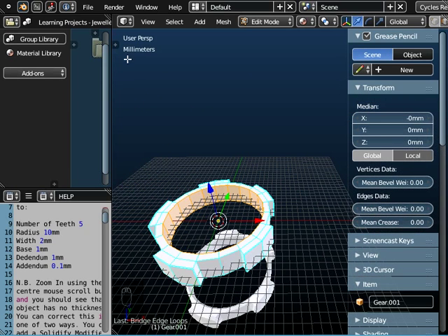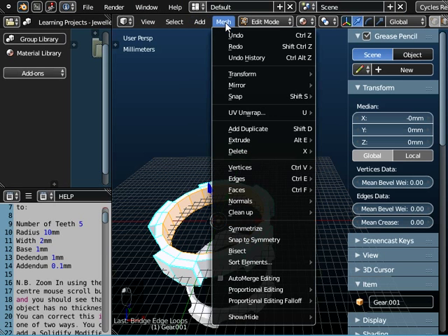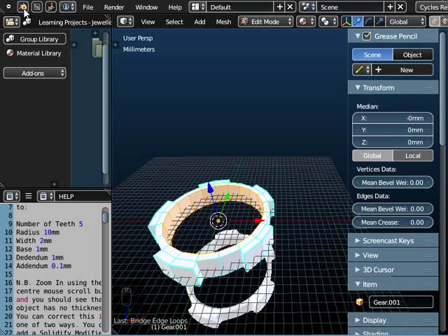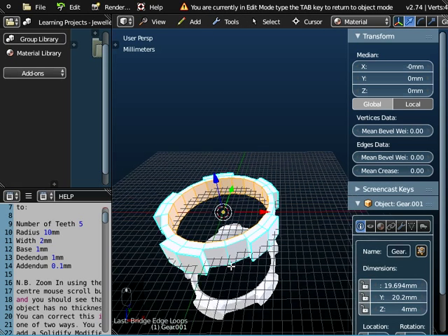Okay, so that's in the Blender menu system. We can switch back to FluidDesigner by clicking on the Blender icon again, and close that down by clicking in the left hand corner. So you can see the menu for meshes has disappeared now. To open it up, click the plus, click Blender, that gives you the mesh interface, the mesh menu. Click the Blender icon and click the icon next to it to return to FluidDesigner.